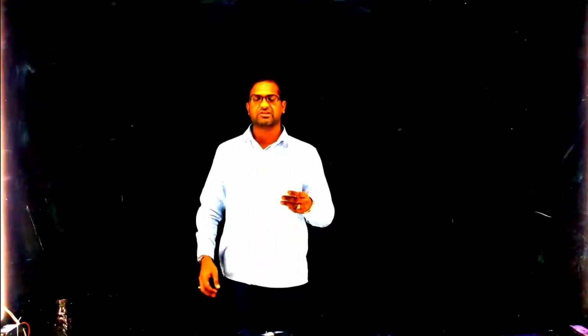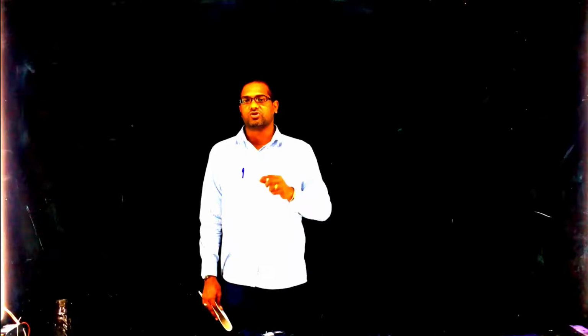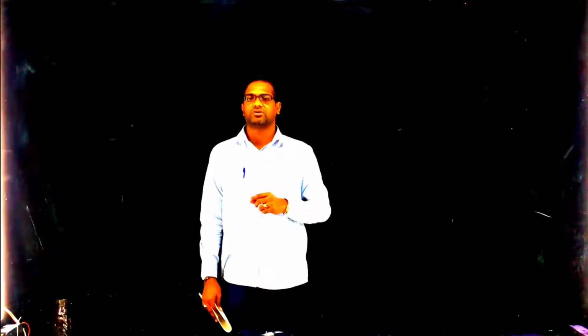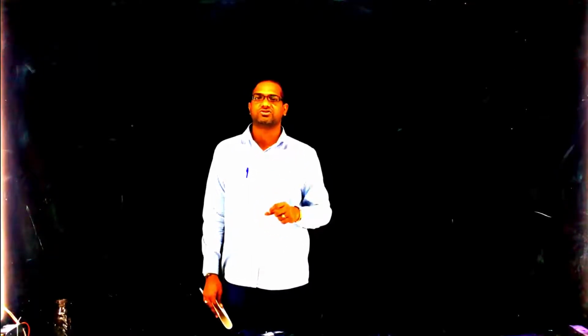In clause number 41.3.1, page number 75, follows the criteria of design stipulations. Now you might have learned in strength of materials that if a member is subjected to torsion, shear stresses are induced in the structure. So when a beam is subjected to torsion, we have to ensure that the beam has sufficient shear capacity.